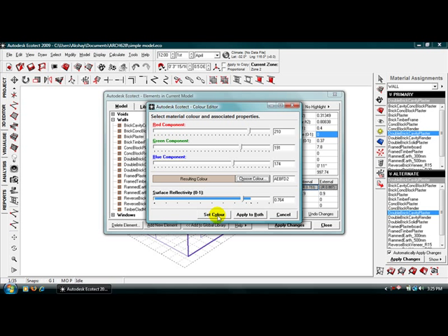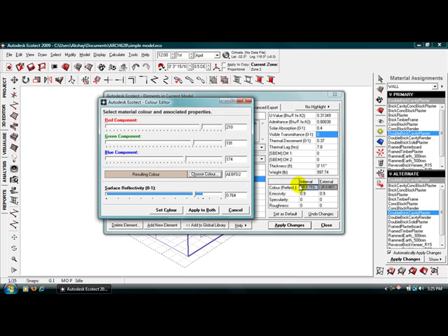And then you have these two buttons over here. The set color button: if you click on it, the color that you have chosen will be assigned only to the type of surface that you selected before. Now since we selected internal surface, if you hit the set color button, only the internal surface color will change and the external color will remain as it is.